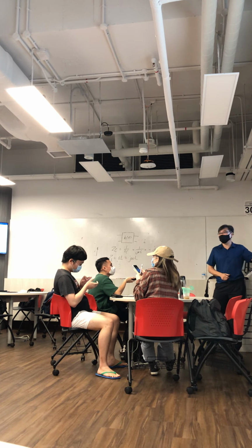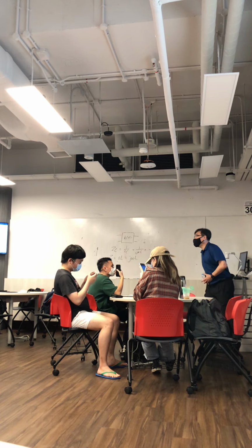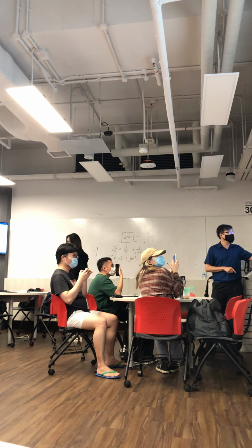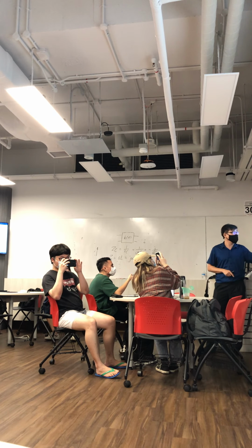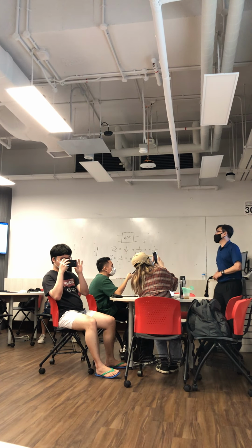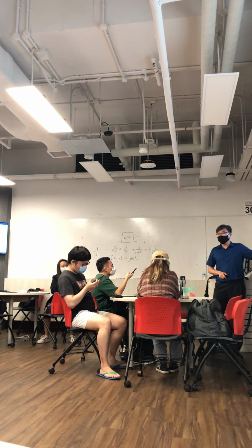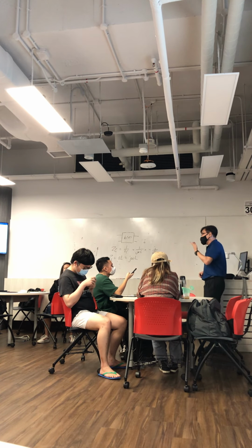Why first order? Because there's only one pole, only one simple one. There are no squared poles and so on. So for this, I can change it from the complex number into phase and magnitude. If your frequency is exactly equal to this pole, you notice that it's exactly 3 dB.